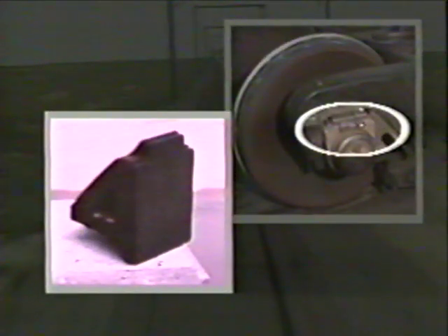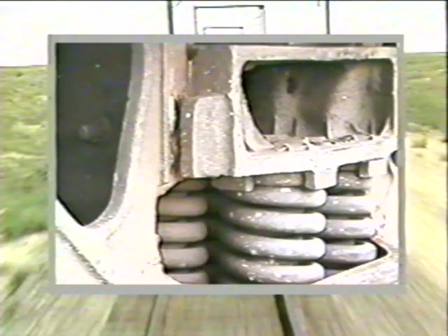Elastomer-coated snubbing wedges and elastomer-bearing adapter pads are intended to be used on specific truck designs and should not be applied improperly. An improper application of these devices may lower a truck's warp resistance. Gib clearances affect the maximum amount that a truck can warp. Worn gibs increase the maximum truck warp angle and the chances of a flange climb derailment.